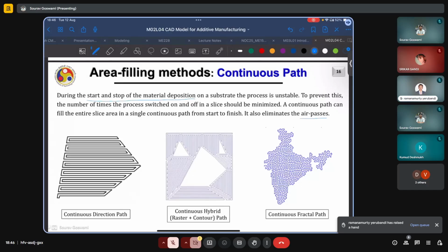Maybe, say, if on the same build plate you have multiple parts being printed, or you specified your toolpath so that it finishes in one place and the next loop starts from some other location, and so on. In this air pass, the head will simply be moving without depositing any material or with the laser switched off. Typically, it will be a rapid motion, but even then it consumes time.